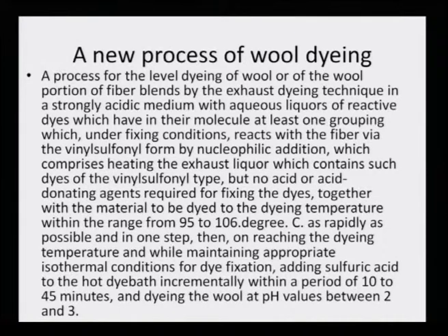fixing the dyes, together with the material to be dyed to the dyeing temperature within the range of 95 degrees to 106 degrees centigrade as rapidly as possible and in one step.